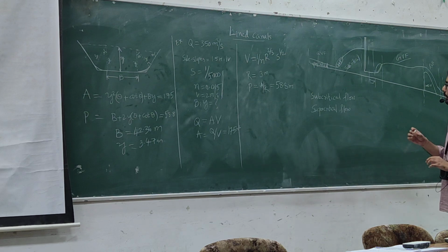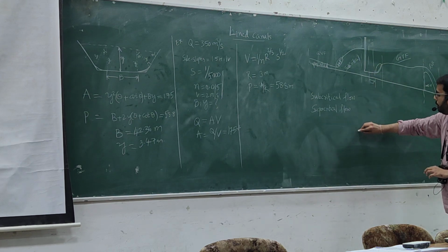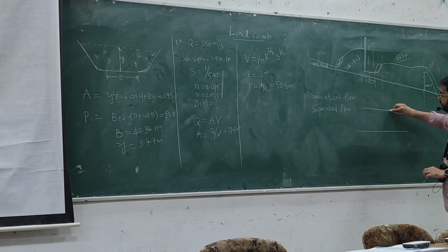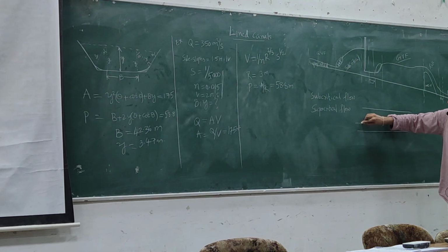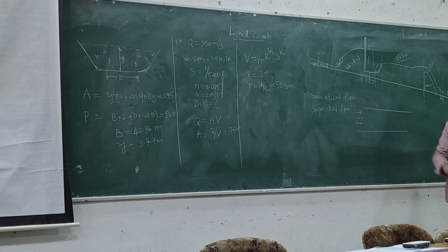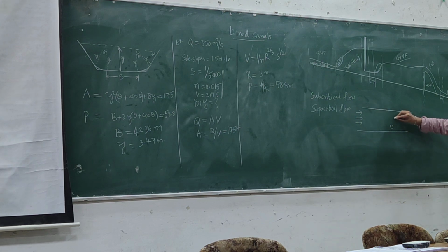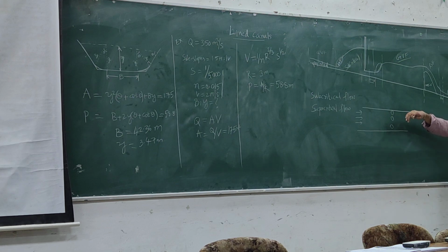Now, let's say we are looking from the top. This is our canal, and there is flow here in this direction. And I have put a bridge on the canal. So if I put a bridge on the canal, of course the flow is going to get disturbed. Let's say if the incoming flow is subcritical, do you see the flow disturbances propagating upstream or downstream or both?